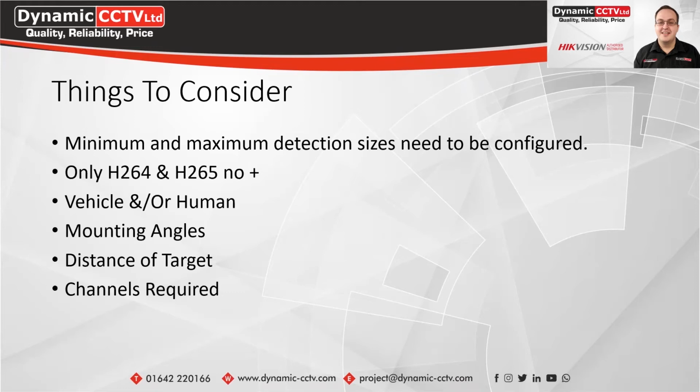You've also got to take into account the mounting angles for the cameras. If the camera angle's too obscure or anything like that, and it can't actually see the person correctly before entering the zones, that can have an effect on the actual algorithm and make it less reliable for your detections.